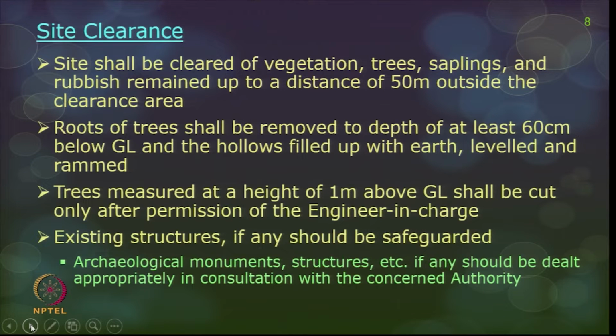Then the next step is site clearance. As I told you, you may have to first clear and level the ground before you start with your excavation. So, what all should you think of for site clearance? Before site clearance itself, if there are usable existing structures, some trees which you want to safeguard, or archaeological monuments and structures, then you should get proper permission for safeguarding them, so that your excavation work does not damage them.